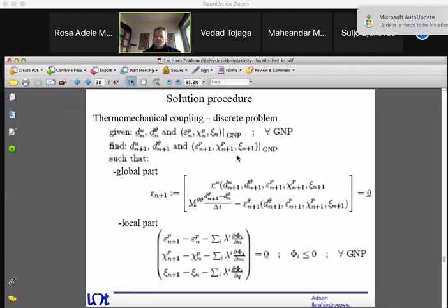On top of that, here you have the equilibrium equation, and again, temperature dependence comes in from the temperature dependence of the properties. So on top of these global equations that concern all the nodal values of displacement and temperature, for shells like that you have 6 degrees of freedom, 3 displacements and 3 rotations, for every node, plus the 7th degree of freedom, which is the temperature. So for every node you have 7 degrees of freedom. And for every Gauss point of such a shell element, you also have to compute how the inelastic deformation is evolving, that means plastic deformation and then bending and something like that.